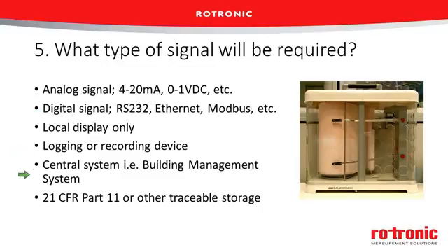Often this information is going to go back to some central system, whether it be a continuous monitoring system or some type of building management system. But we need to look at, okay, what are the requirements from the software, from the hardware associated there? What do they need to see from our instrument? And perhaps we're in a regulated market. Life science customers, for example, might have a need to meet the requirements set out by 21 CFR Part 11. This defines having some traceable storage and some security around the storage and security around any digital signatures around the data. So does our instrument allow us to meet the requirements of this standard?